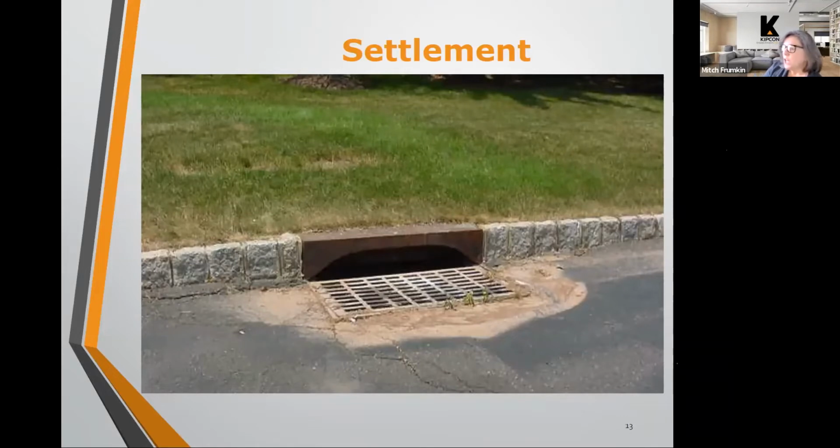Also, changing out what's called the curb piece, which as you can see, is this metal piece along the curb with the opening here. NJDOT, which is the standard we refer to in our specifications, requires that those open curb pieces be removed and replaced with what's called an eco head. It just has smaller openings in it, and it keeps debris from going into the community's